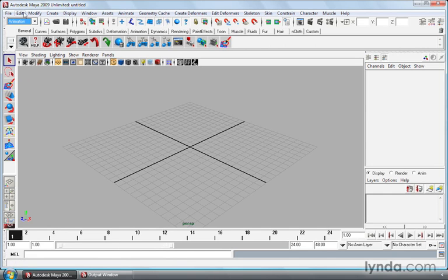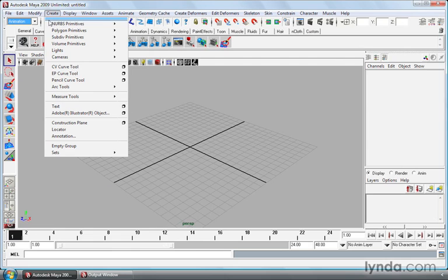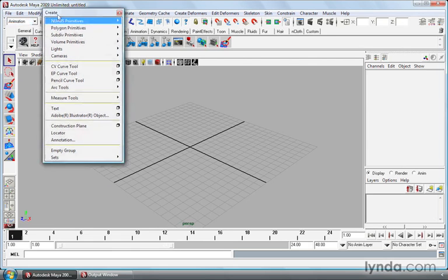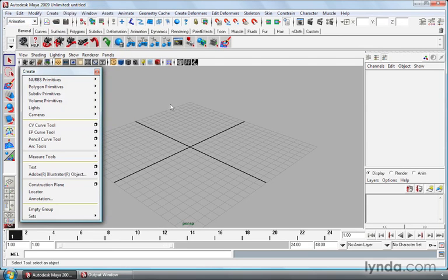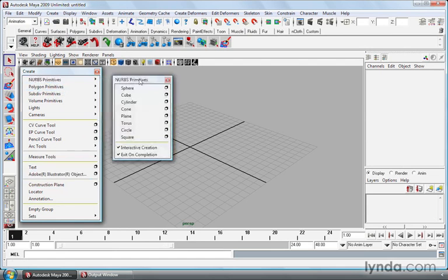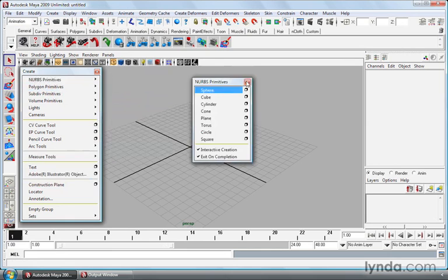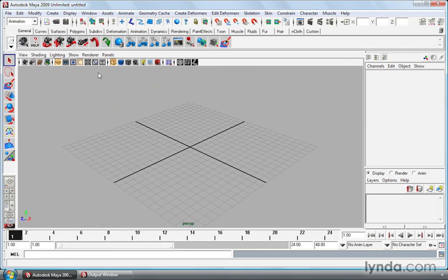Now, another thing with menus is that they can tear off. So click on a menu here, scroll down to this double bar at the very top of the menu. I can just click on that and it floats the menu, which is kind of nice if you need to keep referencing a specific menu. I can also tear off sub-menus as well. So any of these menus can be floated, which will make things a little bit more efficient.